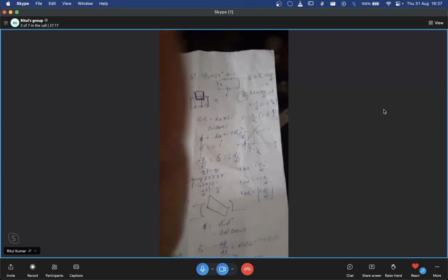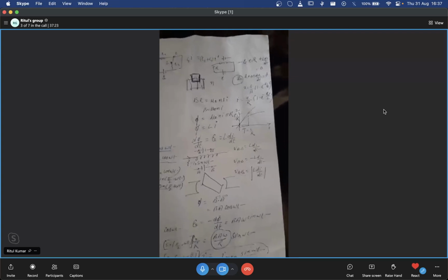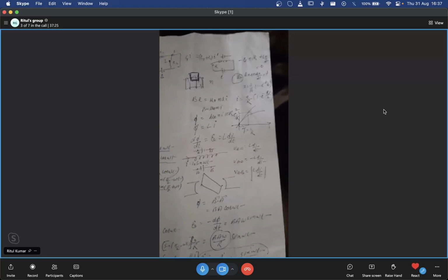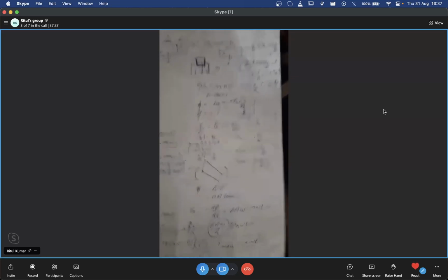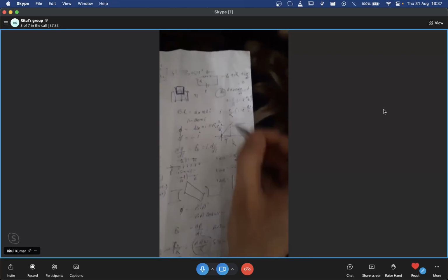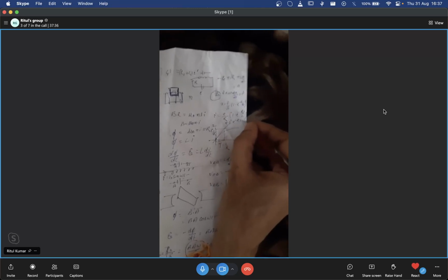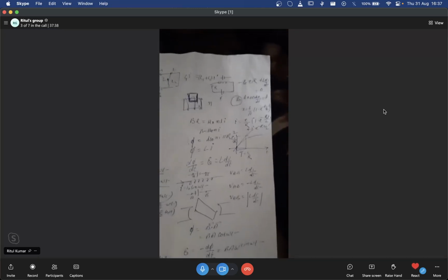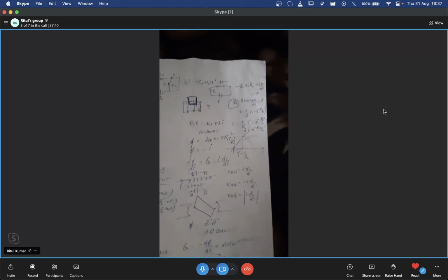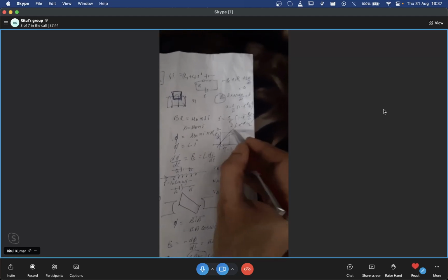So this is what is charging of the inductor. If there was a current I already flowing in it, and if I was in the same direction as that of the eventual current, then you will simply add I e raised to power minus RT by L to your equation. Do check. If it was in the opposite direction, minus I e raised to the power minus RT by L, where I will be the initial current flowing through it.